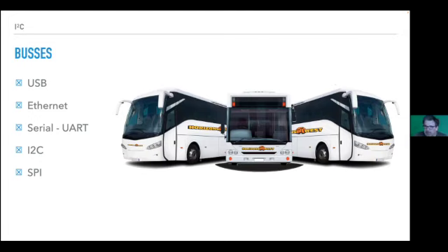Similar with that, probably before I2C came out, SPI, which is also serial, so this is like some serial protocol interface to also talk to the different devices. And I2C and SPI were the two versions I was considering. USB, Ethernet, and serial weren't really useful, also because a lot of those sensors don't talk USB, Ethernet, or serial. So you have to have something that converts from what they talk to another protocol.